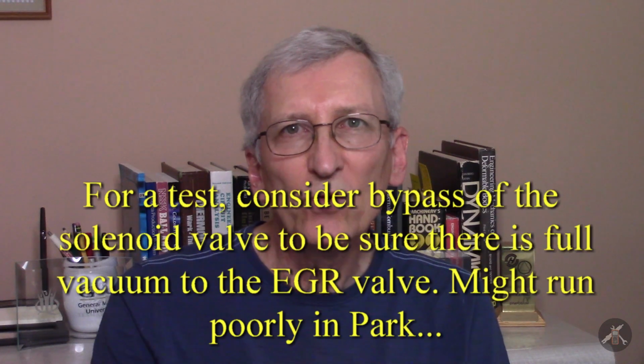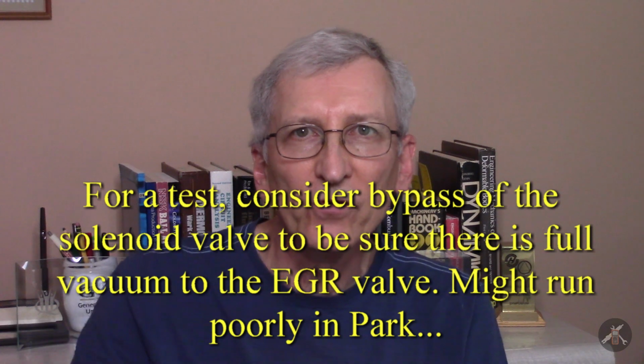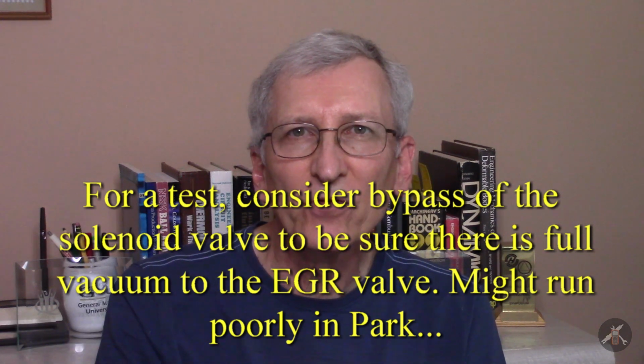And that's how they want it to run. The main thing should be your valve, when you're in your test point, your solenoid valve should be off so that full vacuum goes to the valve, and as you're tipping in the throttle, whatever the ported spark will do to drive the EGR valve should be what you get. You should get opening from that.